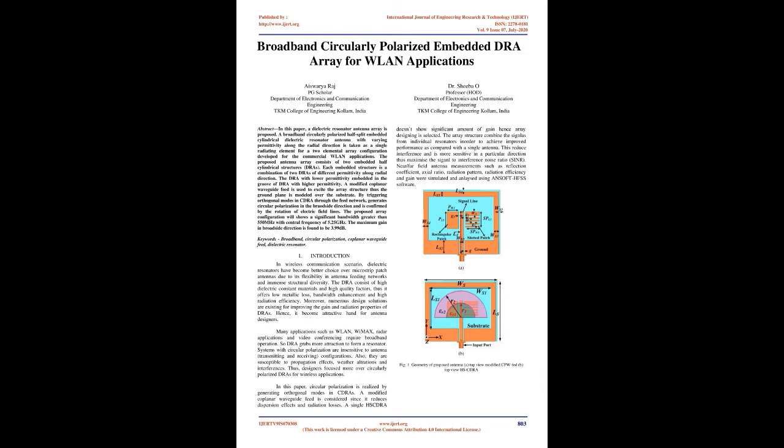Introduction. In the wireless communication scenario, dielectric resonators have become a better choice over microstrip patch antennas due to their flexibility in antenna feeding networks and immense structural diversity. The DRA consists of high dielectric constant materials and high quality factors, thus it offers low metallic loss, bandwidth enhancement, and high radiation efficiency. Moreover, numerous design solutions exist for improving the gain and radiation properties of DRAs. Hence, it has become attractive to antenna designers.